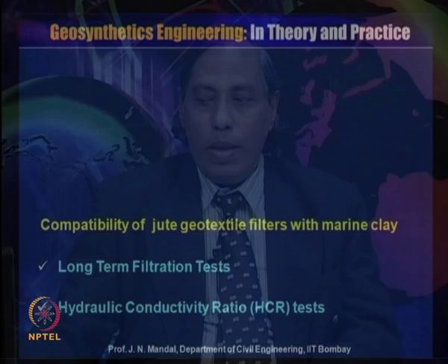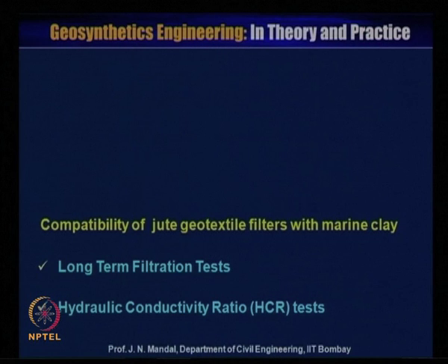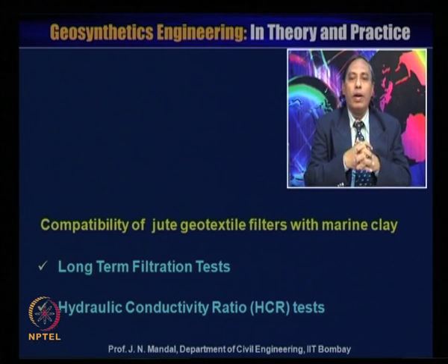Then some compatibility of jute geotextile filter with marine clay, because the jute geotextile will come in contact with the marine clay when you install this prefabricated vertical drain. So, what is required? A long term filtration test.